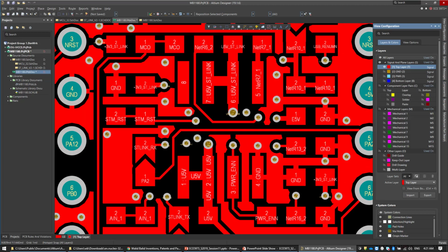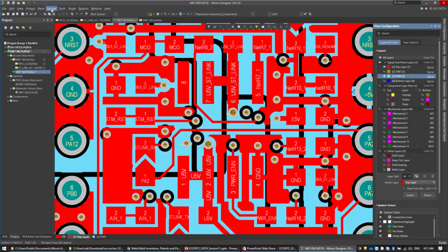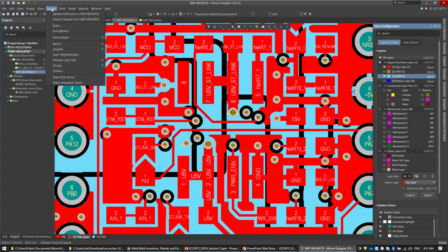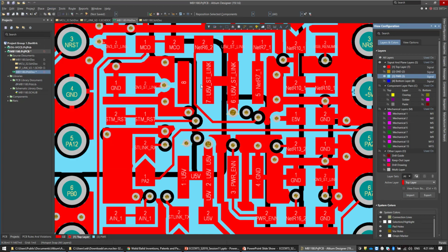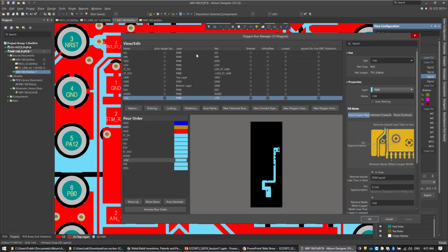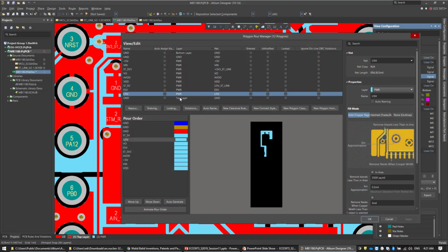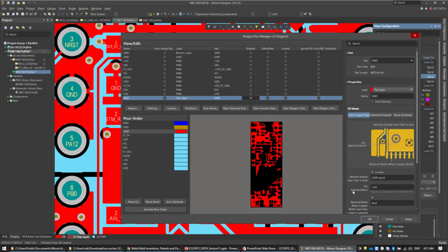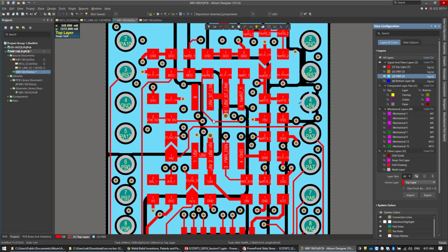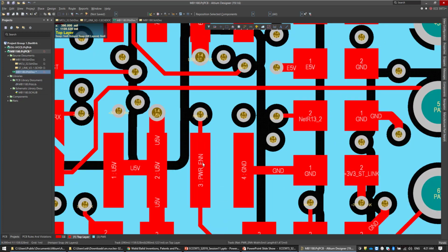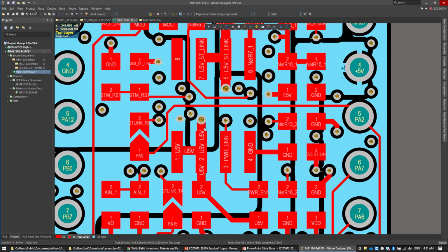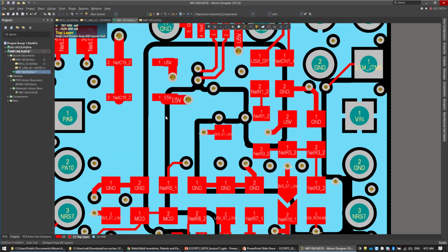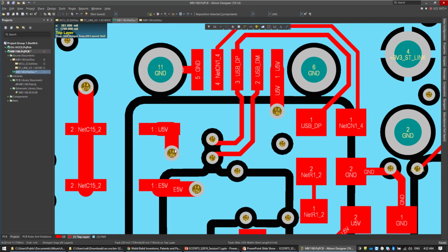Let me show the power layer in here. This is the power. Let me hide the polygon. Design tools, polygon pour. I need to hide the polygon on the top layer. This will make it more clear. Okay. So here, you see, this is about here. 5 volt goes in here. It's just a branch and connect from inside. The other one goes up here. So branch and connect inside.